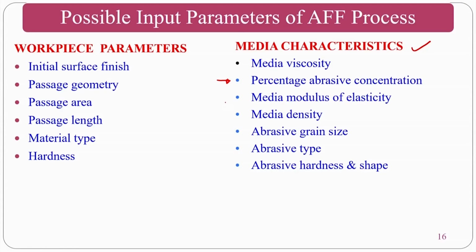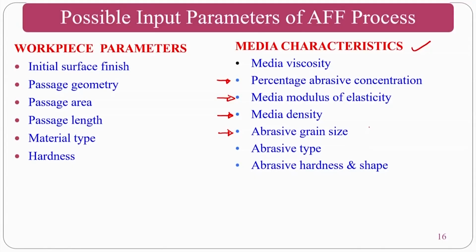Medium modulus of elasticity and medium density will also improve the abrasive action. At the same time, if the abrasive grain size increases, what will happen? The indentation will increase. If this is a small abrasive size and this is a larger abrasive size, then for the same extrusion pressure and other conditions, the indentation created by the larger abrasive particle will be more. So the material removal will be more.